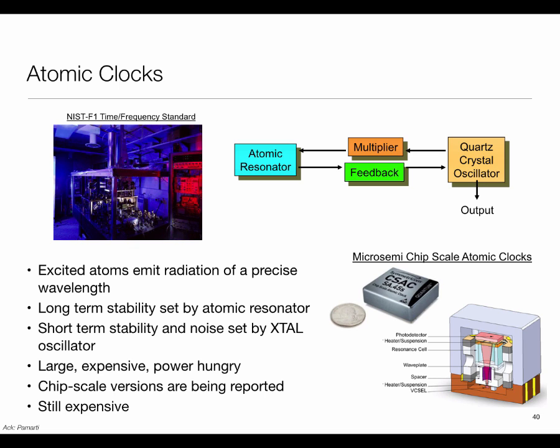Handheld radios, because if they can synchronize very easily, a device can go to sleep saying, I'm going to wake up and communicate. So the two parties can say, we'll wake up a month from now and I'll send you bits. And if the clocks are very stable, then you wake up and just start squirting out the bits. You don't have to do any synchronization at that stage. So you can get great advantages that way.